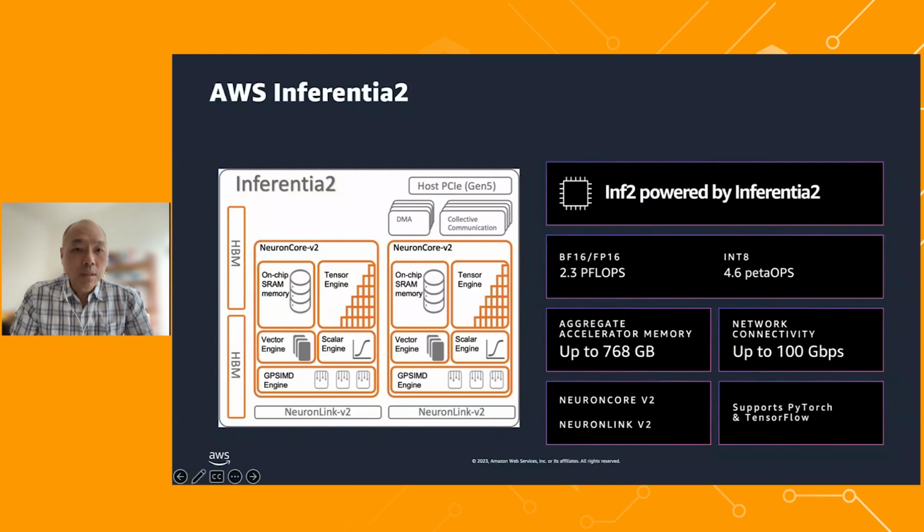And within that particular Neuron core, this is where things start to be a little bit interesting. You notice that we separated out into 3 different engines: a tensor engine, a vector engine, and a scalar engine. And this is exactly like how Arun previously explained. The tensor engine handles large matrix multiplication jobs, the vector engine handles aggregation, and the scalar engine handles operations such as activation functions.